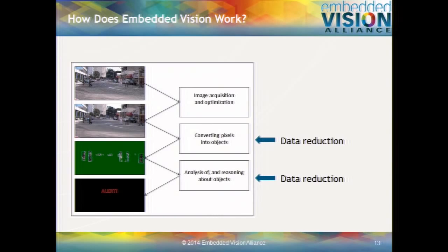Now, of course, cameras do this, but they are optimizing for different criteria. They're optimizing for a pleasing looking image that we're going to look at and say, yes, we like how that looks. For vision, we're optimizing for different criteria. We're optimizing for maximum information, in some sense of the word information, in the image. Once we've gone through those steps, which include things like contrast enhancement, noise reduction, color correction, lens distortion correction, then